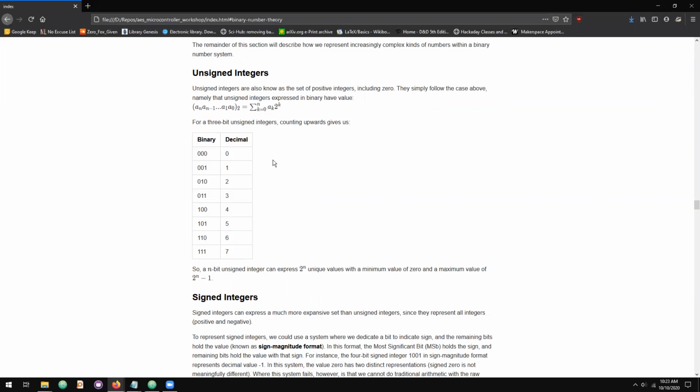So in embedded systems, we can do things like representing a state as a counter. It doesn't mean anything reasonable to have a state that's a negative number. So we can represent a state with a counting value that's just represented as a binary unsigned integer.